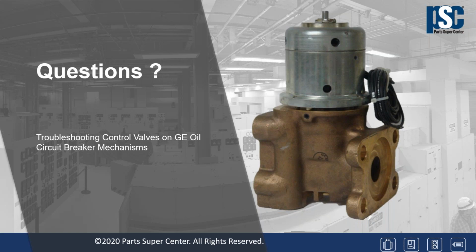And so one of the things you want to look for if you're closing slow is that you don't have a damaged coil, you don't have excessive pilot armature spring bias, and that screen that we talked about, that inlet screen on the side of the valve that has the O-ring, you want to make sure that that screen is not all clogged up. That screen has two different layers, a very porous layer to capture big particles, and a very fine screen mesh to capture smaller particles.